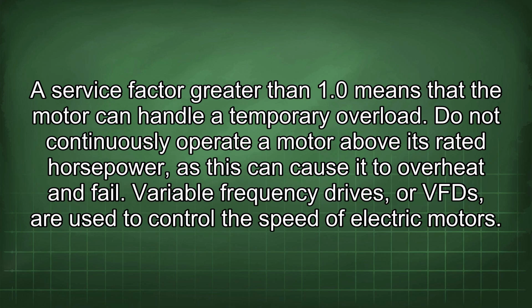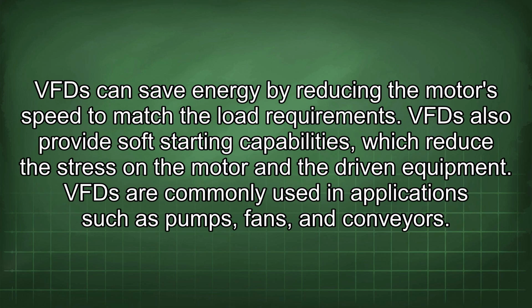Variable frequency drives, or VFDs, are used to control the speed of electric motors. VFDs can save energy by reducing the motor's speed to match the load requirements. VFDs also provide soft-starting capabilities, which reduce the stress on the motor and the driven equipment. VFDs are commonly used in applications such as pumps, fans, and conveyors.